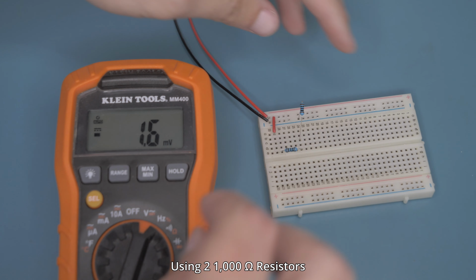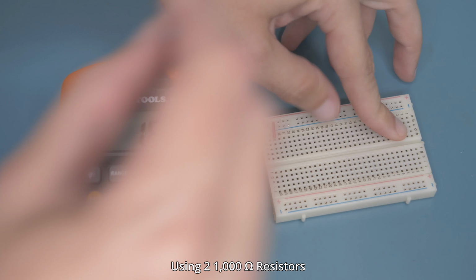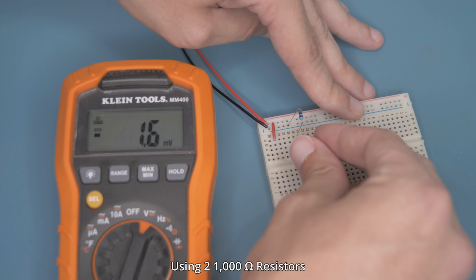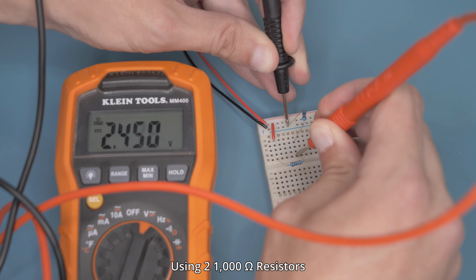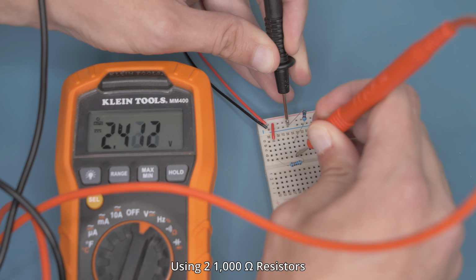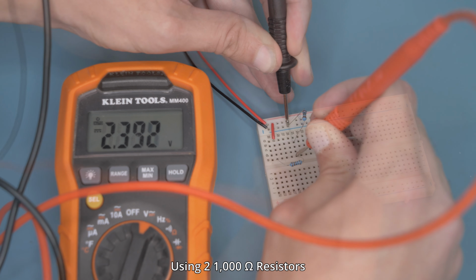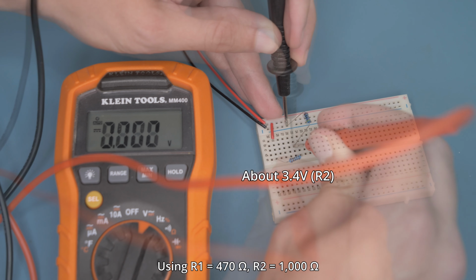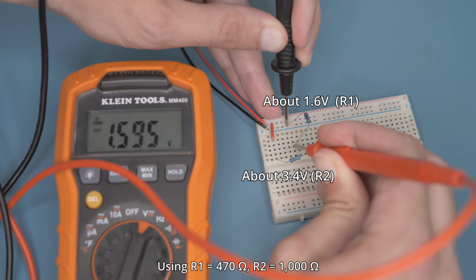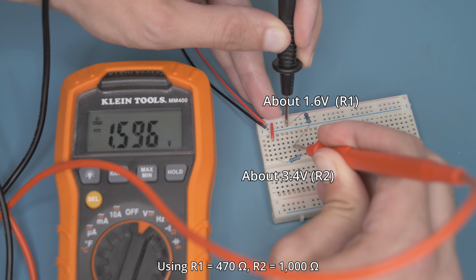Likewise, if we use two 1000 ohm resistors, they will each still have 2.5 volts across their leads. The voltage remains the same in these two scenarios, but the two 1000 ohm resistors will have a lower current passing through them. If R1 is 500 ohms and R2 is 1000, we will see 1/3 of our supply voltage over R1 and 2/3 over R2. The voltage is divided proportionally between the two resistance values.